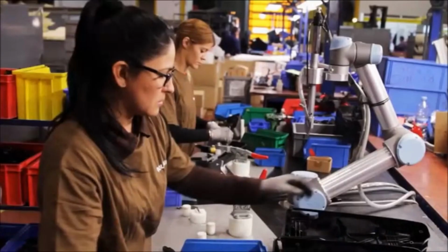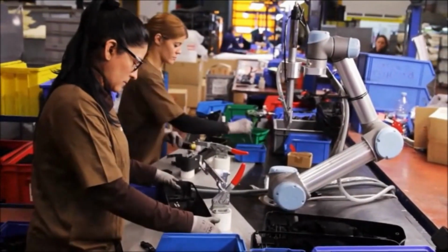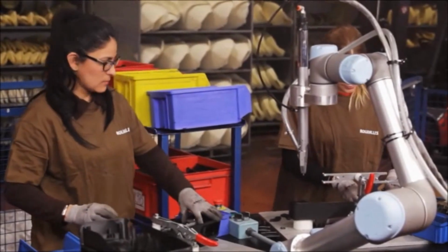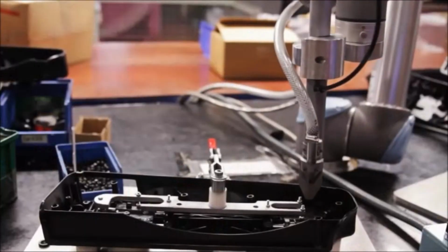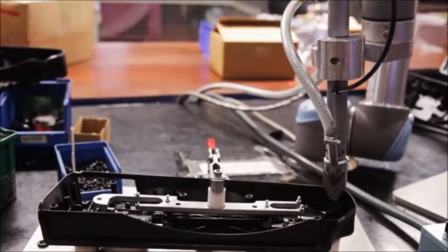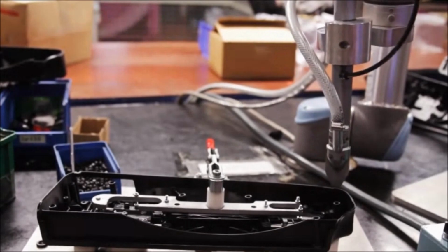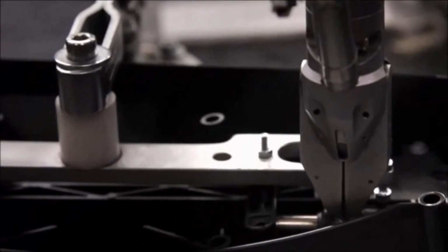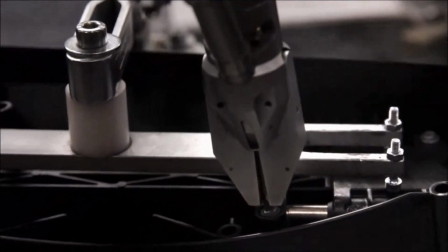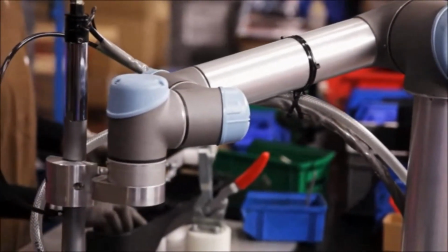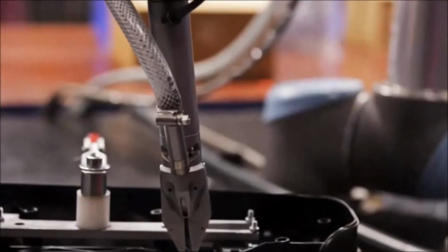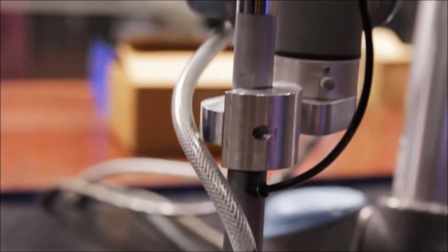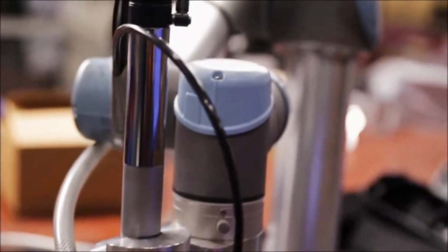On accuracy, be cautious with lesser known or lower cost cobot brands. Some of these brands publish accuracy and repeatability specifications that are only achieved under very specific conditions. When you replicate those conditions on a real production floor, the actual cycle time increases significantly. You end up with a robot that does not perform as you expected. My recommendation is to request a live demonstration using your actual part and your actual process before you commit to any cobot purchase. Reputable brands will accommodate this.